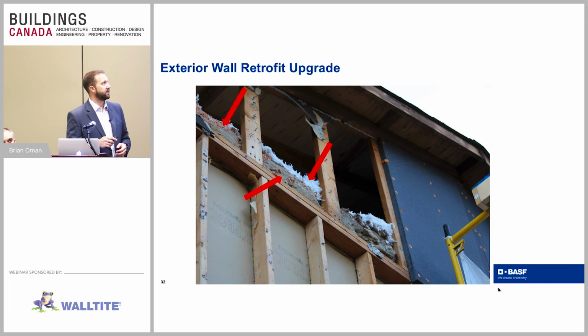I can't tell you what the R value of this is because we don't really know. It's multiple components coming together. You can't necessarily take an assembly R value out of that due to compression of the insulation, age of materials, and differentiation of materials.